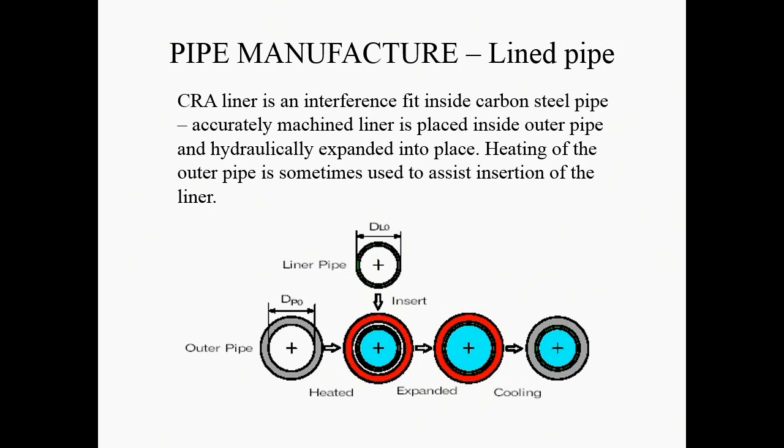So it's rare that anybody would use a seamless pipe that couldn't be made by this tube insertion method, because it would be so expensive to set up something for a corrosion-resistant alloy, and the volume of corrosion-resistant alloy you need is large, so the expense is very high. So generally cost drives everything, and if you can get away with a plain carbon steel with whatever thickness allowance or whatever you want to make, that's the best way to do things.